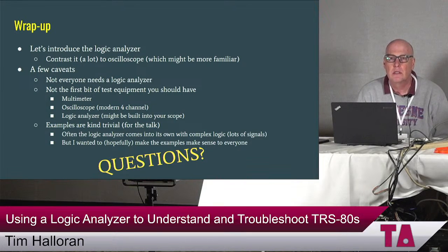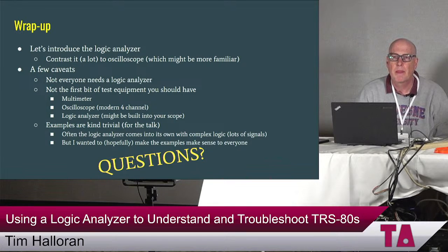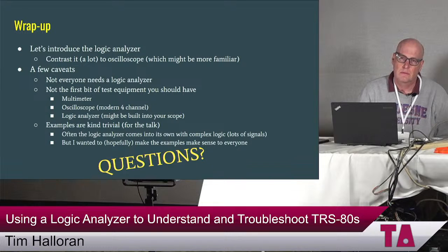The thing with these low-cost signal analyzers is they would be very good if you're designing peripherals. You already know the signal you want to test on your output, and the rate's going to be low enough. The thing about the Bus Pirates is they can support certain protocols. And again, it costs less for the whole machine than probably what the protection circuitry on the high-cost one costs. So sometimes it might be a throwaway if you blow it.